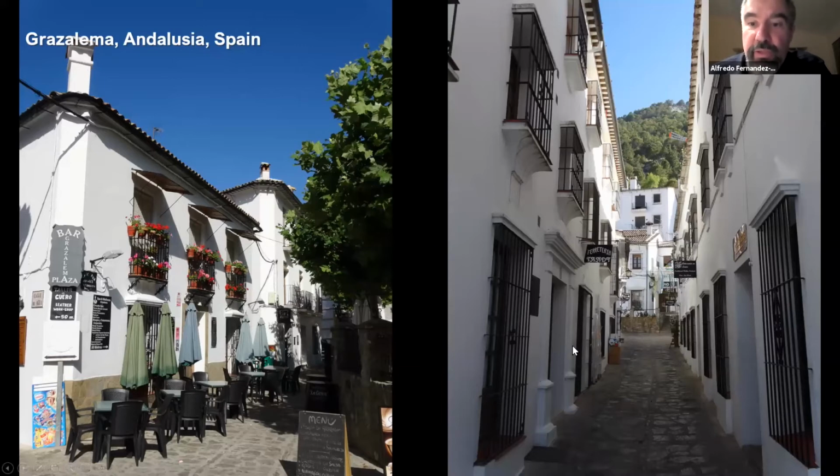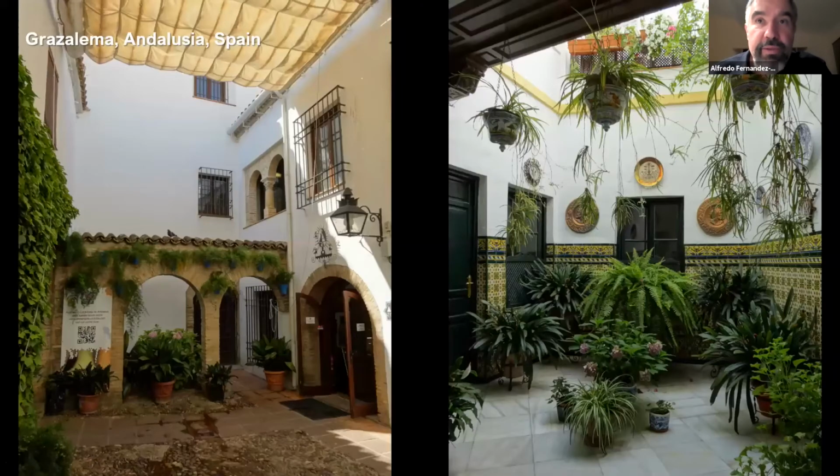The use of light colors also helps reflect solar radiation and reduce heat gain. And these streets therefore allow passersby to remain comfortable. And in terms of privacy and where we can get illumination and ventilation, we use courtyards as a strategy to provide passive cooling, to also provide, as we said, some of the contact with nature and illumination for the indoor spaces.